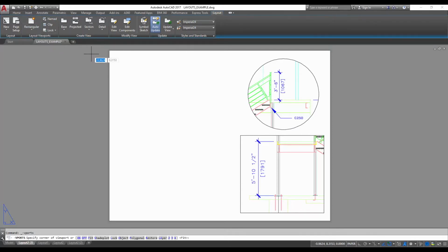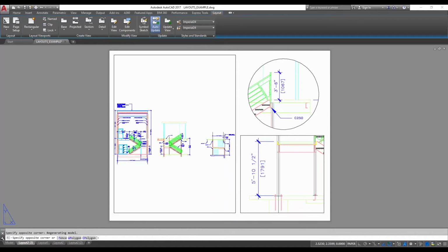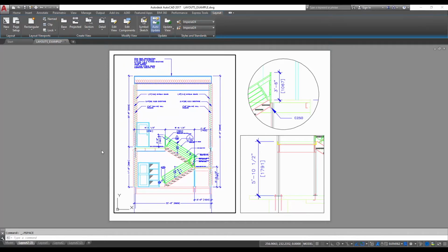Using these methods, you can create viewports to show your entire design or separate details of the design at different scales and angles. Viewports can be made using a variety of objects, including polygons, rectangles, or circles, and can also use the View Cube to modify or change the desired view.